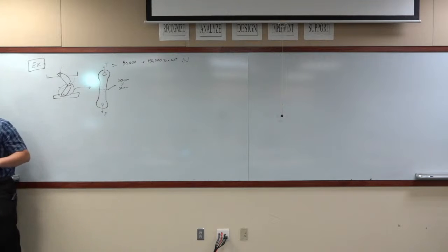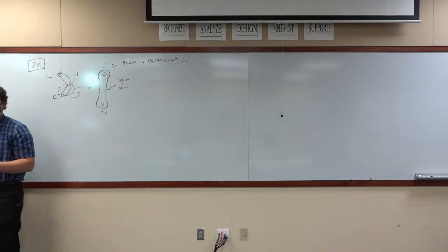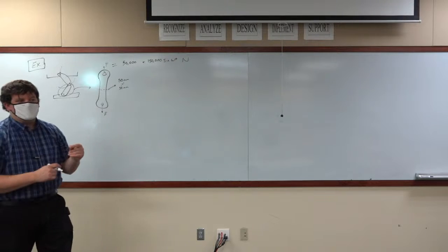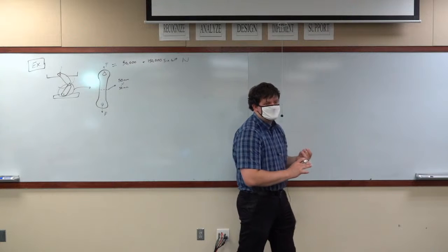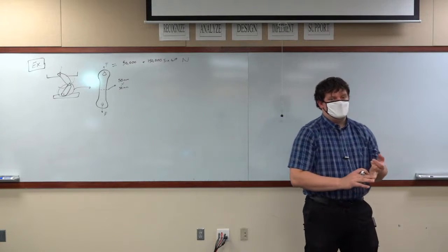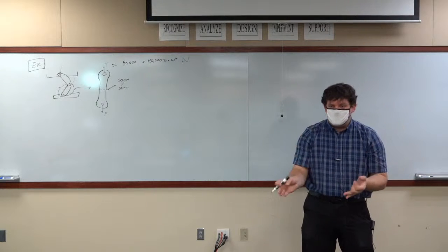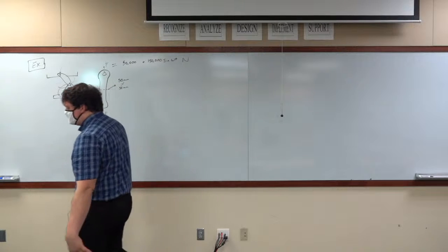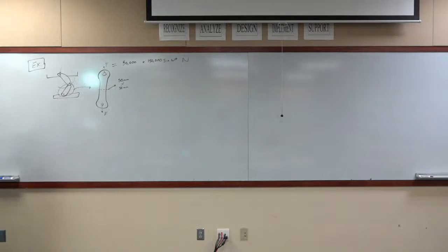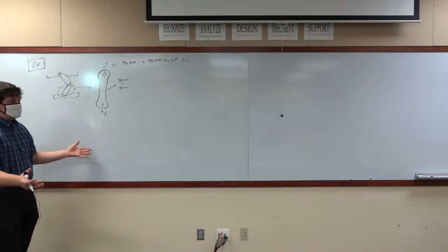Okay, so to solve a fatigue problem, it's the same exact steps as a static failure problem, which we did last week, but we have to add in a few things. First of all, we have to determine the effective stresses, and second of all, we have to figure out the endurance limit. Otherwise, it is exactly the same. So yes, I'm showing you this, and yes, at this point hopefully it starts getting boring. Because if it's boring, it means you understand it. And that's my goal. That's why I'm belaboring this topic.